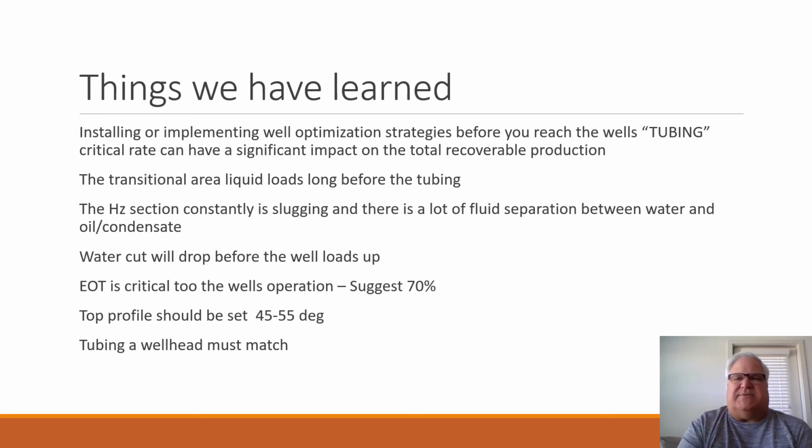We'll also see where two-piece plungers, we'll replace them with free cycle or even with a conventional, and we'll get the same. So there's no guarantee that one plunger is better than the other. You need to match your production to the way the well builds up, how much energy it has, how much fluid it's trying to move, even the way the well has been drilled can impact how that liquid's going to move. So you've got to work through several different trials on each well to figure out what's going to give you the best bang for your buck.